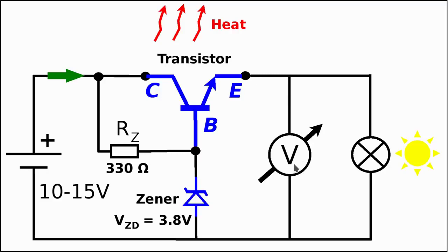Furthermore, we have to have a way to tell this power transistor the input voltage has changed. So now, in order to have the same stable output voltage here, we must also change the resistive value between the collector and the emitter electrode. Also, if the load changes for some reason, we also have to tell the power transistor that it needs to adjust this resistive value between the collector and emitter accordingly. As a long story short, we have to monitor the output voltage actively, and as a function of the output voltage, we have to send back some signal to the power transistor such that the output voltage will be stable.